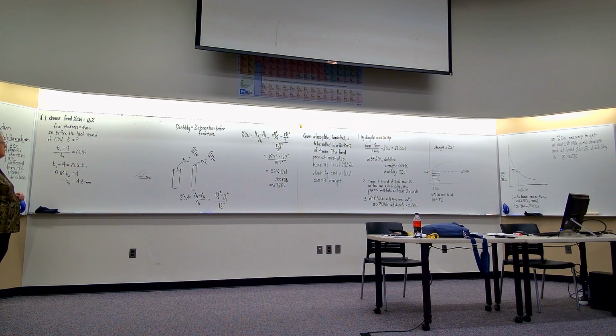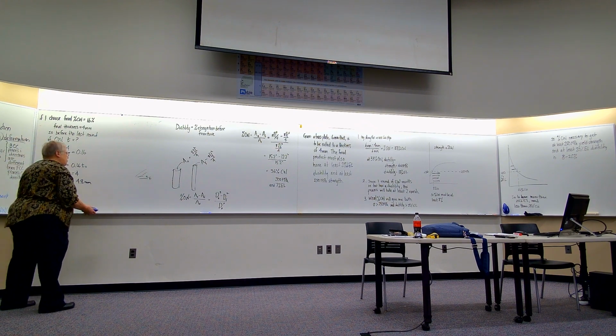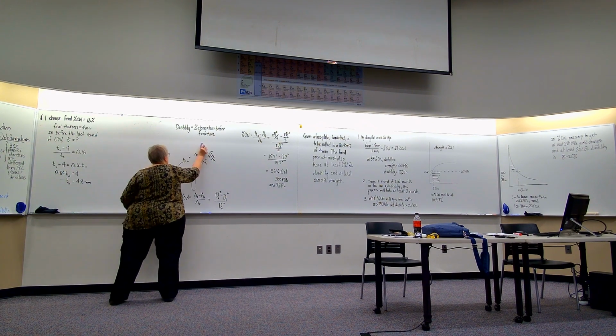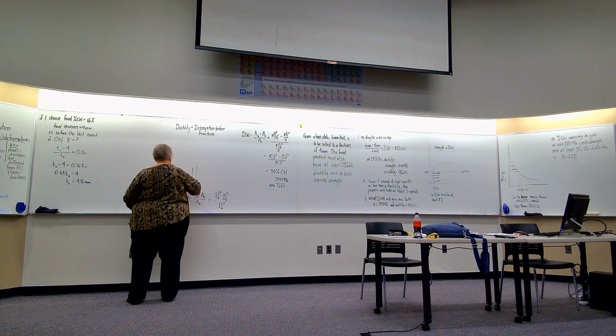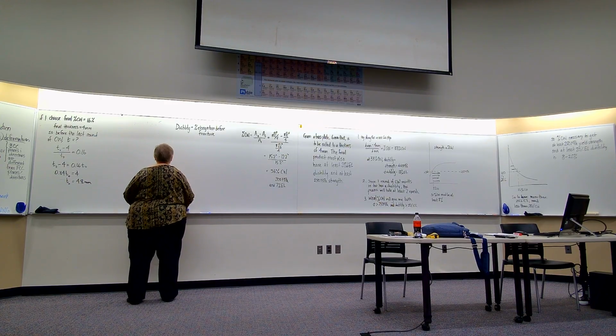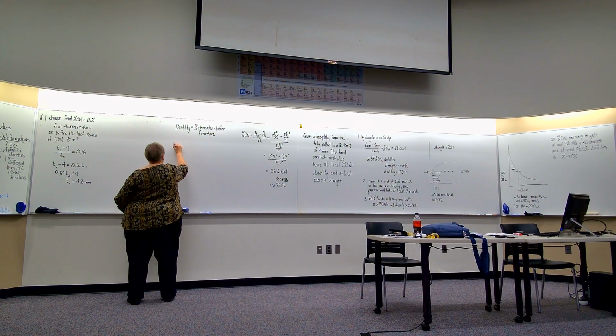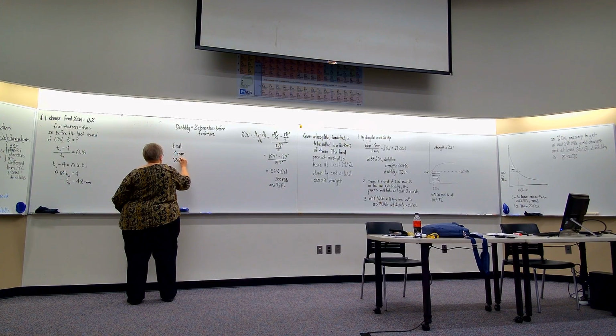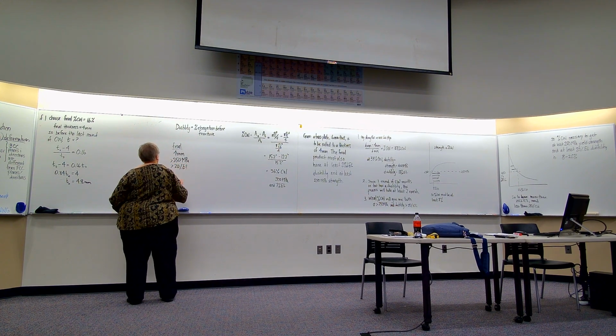All right. So what do we know at this point? We know our final product is 4 millimeters, 250 megapascal or more, and 20% elongation or more.